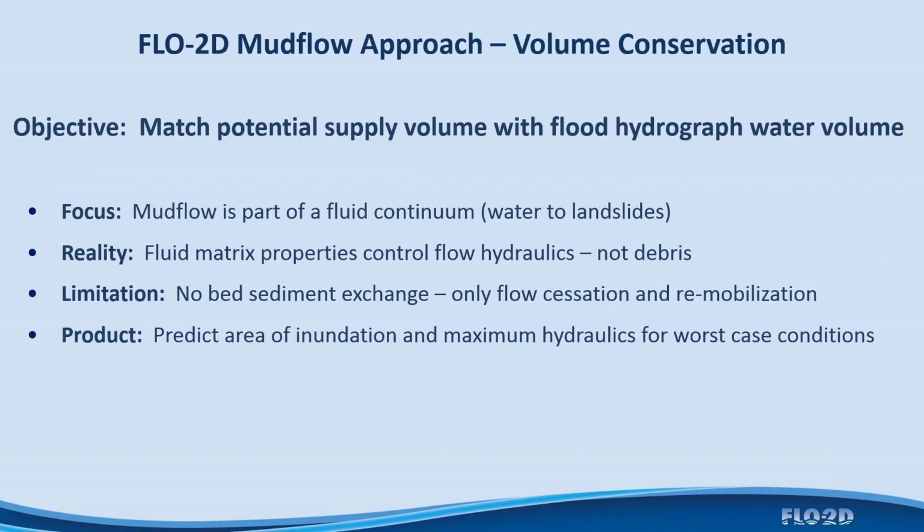The approach in Flow2D is a volumetric conservation approach, and the objective is to match the potential sediment supply volume with the volume of the hydrograph that you're trying to model. That might be a design hydrograph or maybe you're trying to replicate a given event that occurred in the past.